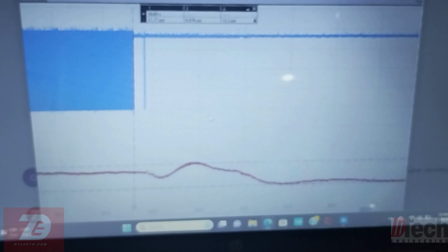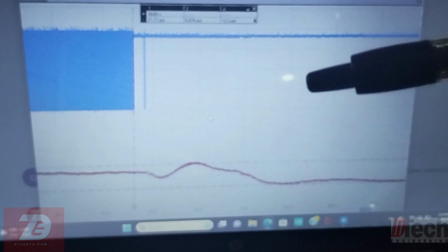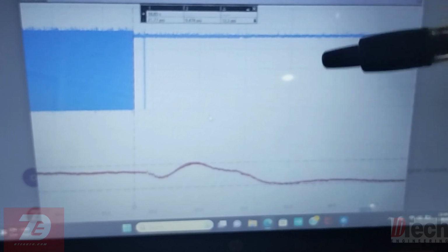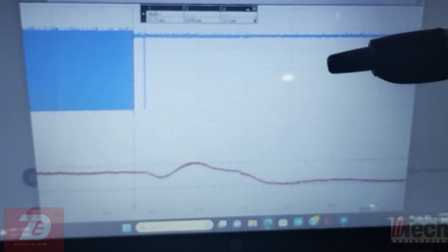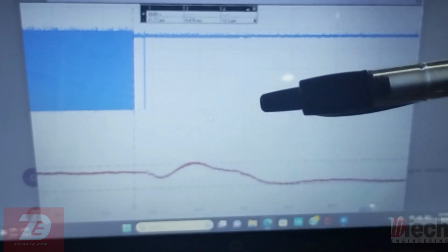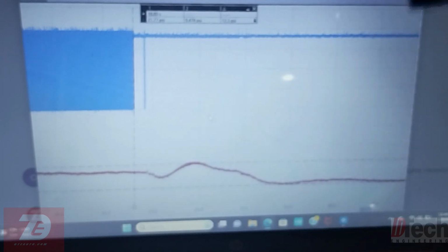So this tells me that we have some sort of mechanical issue, and it is not related to the control valve, it's not related to the DME, and so on and so forth. And we are just verifying that we physically have low oil pressure because of a mechanical issue.